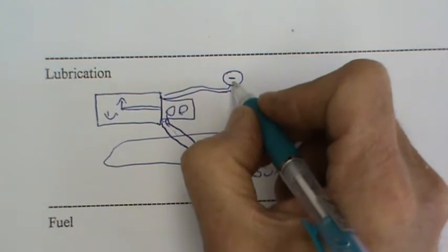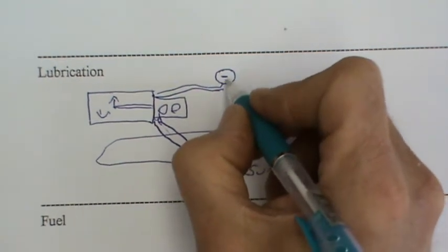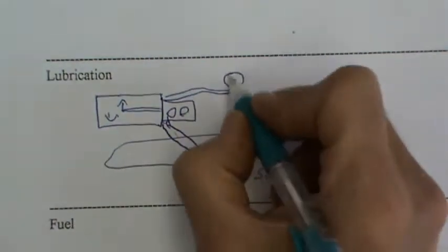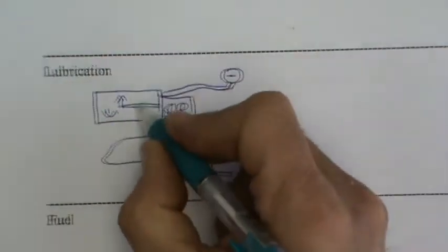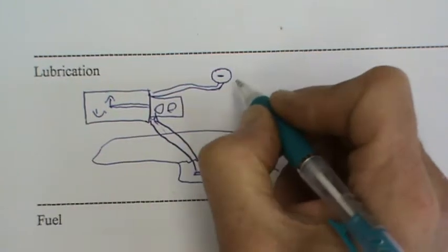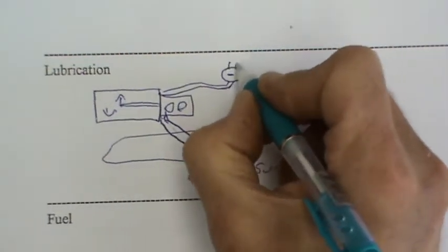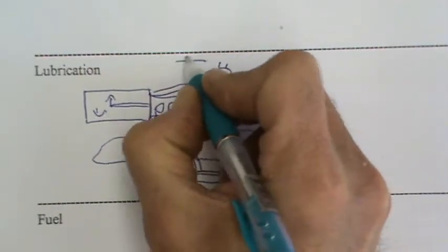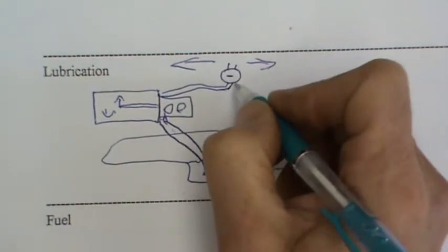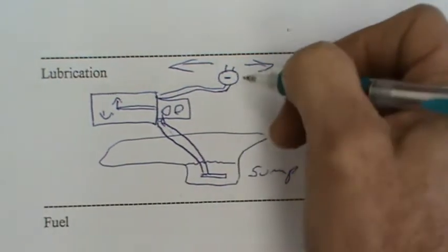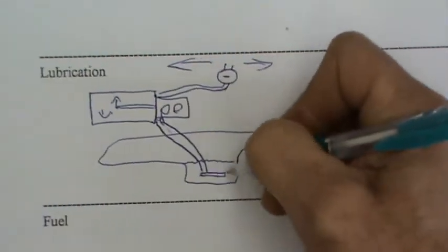When you turn the key on, you should have an oil light showing that you've actually got this system working. When the pressure comes up, it will turn that switch off, and that shows that oil is going out into the whole of your motor. If you're driving along and that oil light comes on, stop. You've only got a few minutes if you've run out of oil.